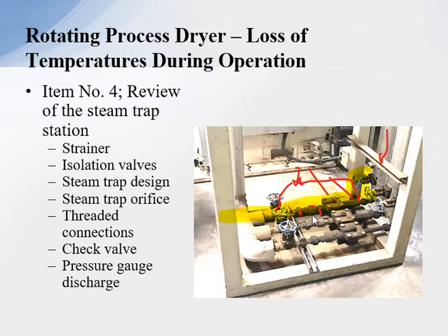The other item was there is a check valve in the system, again restricting the flow. In this particular system there is no need for a check valve because backflow cannot occur. And the last item is putting a pressure gauge here so we know the condensate return line pressure, because the steam trap is a delta P device, P1 at the inlet and P2 here at the outlet. So pressure gauges always tell us the pressures that are occurring.